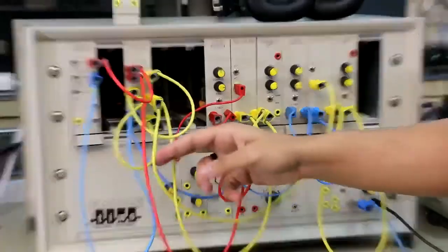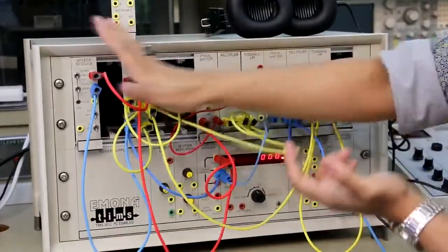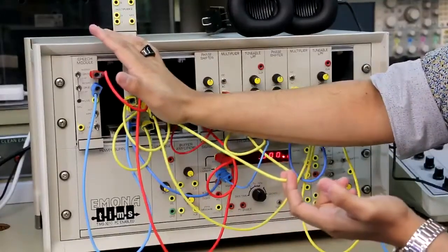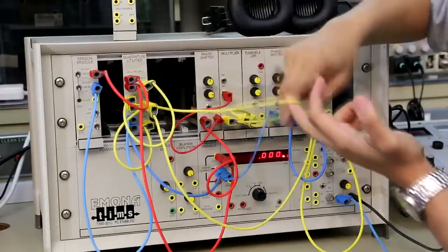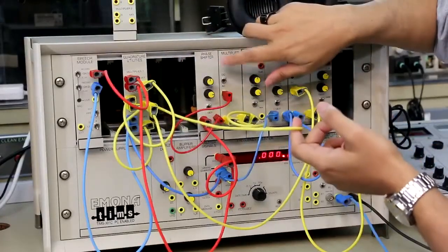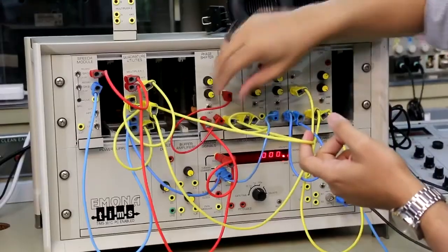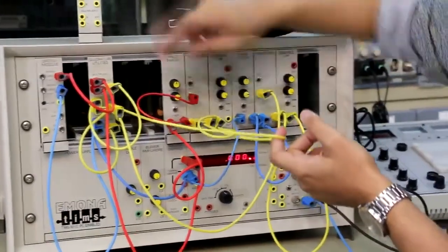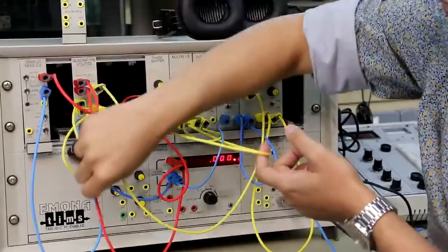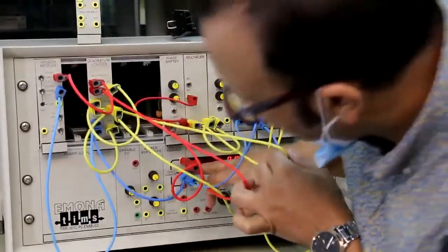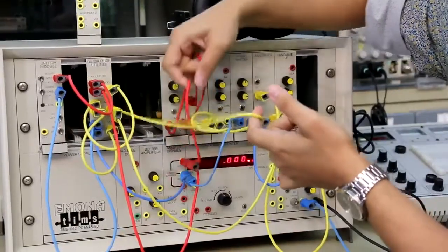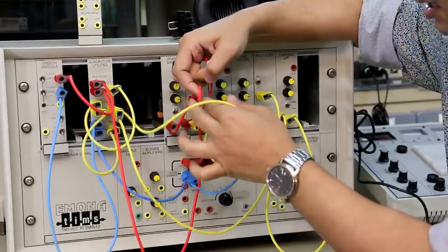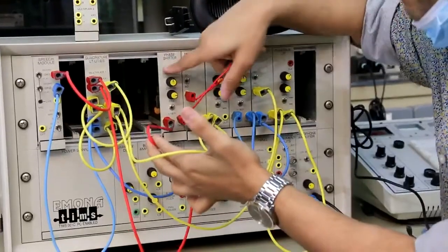Now I'm taking the QAM signal as an input to my demodulator. This is my modulated signal, and now this is my demodulator. On the demodulator side, the QAM signal goes to a multiplier, because I want to get message 1, which was multiplied with sine, so my QAM signal is multiplied with a phase shifted sine signal, and we'll see the effect of the phase.